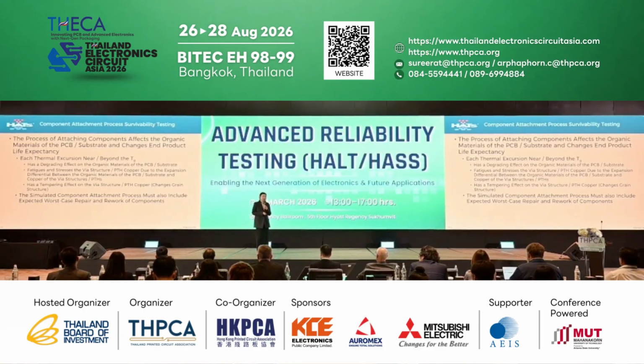It will fatigue and stress the via structures and the PTH copper due to expansion of different materials, because the expansion factors are different for PCB materials and the via structures. And it also has a tempering effect on the via structure and PTH copper. It will change the grain of copper structures.